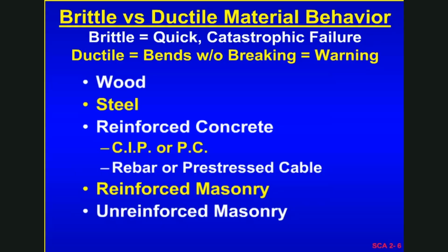Properly reinforced masonry may behave relatively ductilely, where unreinforced masonry is probably our most brittle material, and many, many buildings throughout the U.S., especially the central U.S., in the central earthquake zone around St. Louis and so forth, hundreds of thousands probably of unreinforced masonry structures exist.